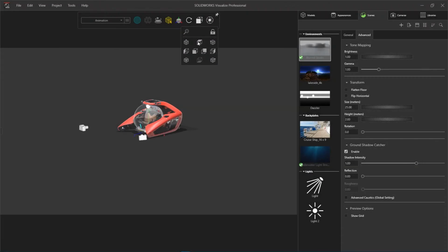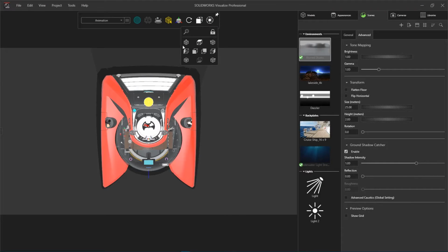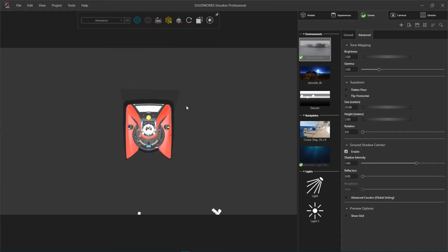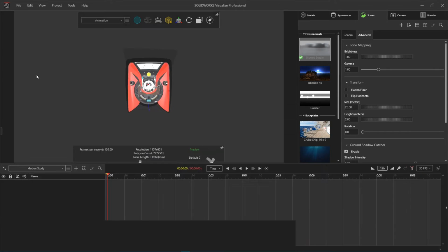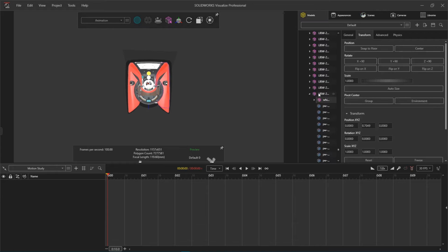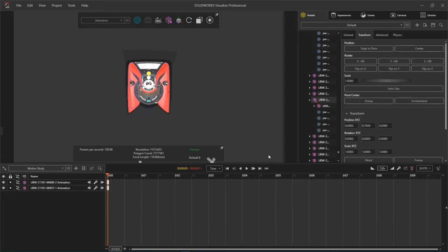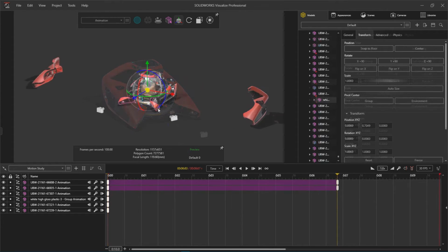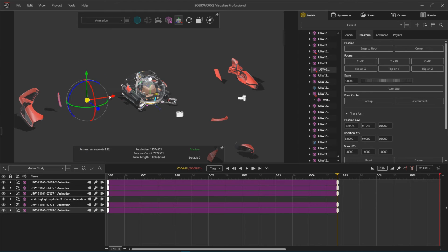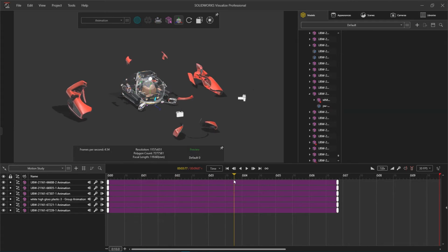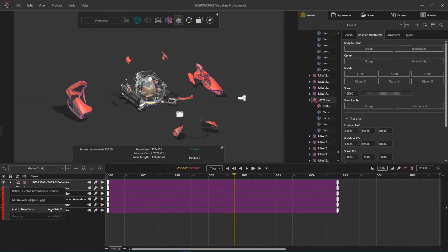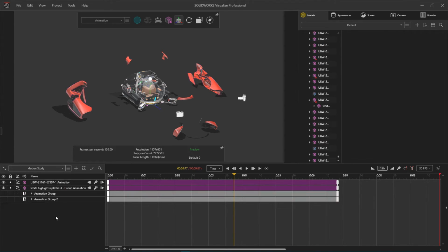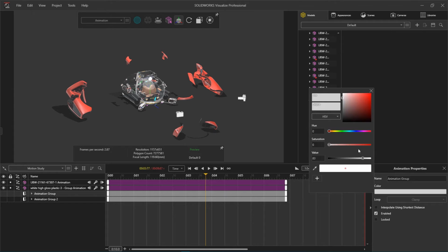For the final rendering, a third configuration is created to capture an exploded animation of the Nemo. With the timeline enabled, groups are selected and keyframed to define their start and end positions. Going through this process of keyframing multiple parts and groups can quickly clutter the timeline. Now in Visualize 2022, items added to the animation timeline can be nicely organized into folders using the group option. The animation ribbon can also be color-coded, making it easy to find and reposition these keyframes right into the perfect place.